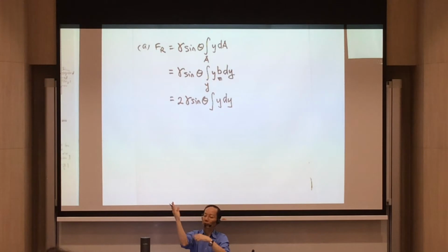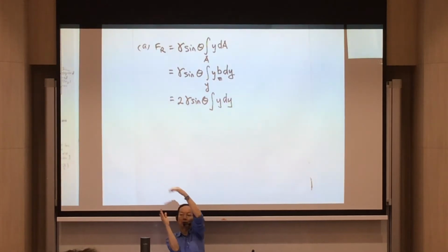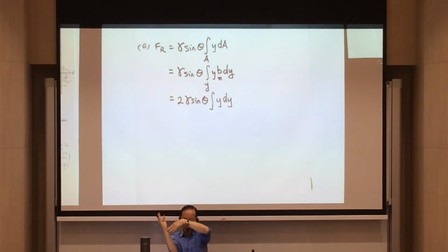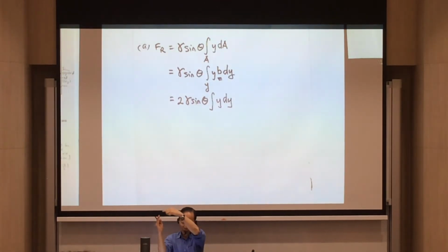So this is the gate, and the water level is up there. The forces vary. We're going to find the resultant force. Because all these forces act along the whole surface, horizontally there's no variation, it only varies in the y direction. So when you integrate across y, you have to go from the top edge of the gate to the bottom edge of the gate. Where is the origin? The origin is of course at the water surface.